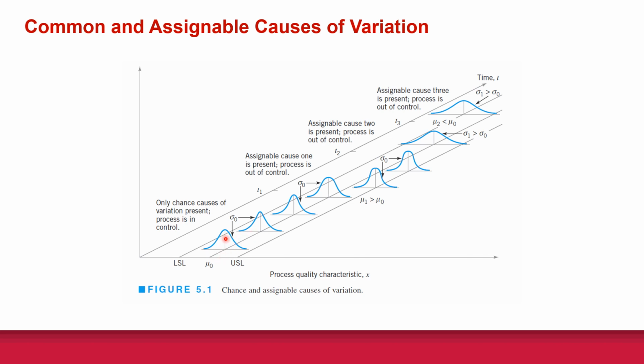So, up until time T1, when we take our first sample here, everything's looking great. Both the mean and standard deviation are within their normal control values. You may look at it and say, okay, well, yeah, but there is some variation. Yeah, that's what's called common variation. Remember, no two products are going to be manufactured exactly alike. There's going to be subtle differences, even in the weight. If you weigh down to a fine enough scale, even dumbbells will have a slight variance.